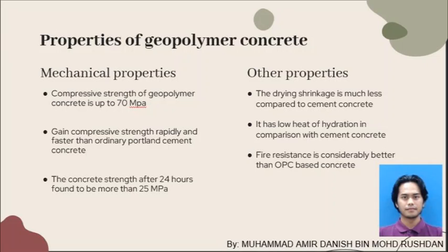The other properties are the drying shrinkage is much less compared to cement concrete. This makes it well suited for thick and heavily restrained concrete structural members. Second one, it has low heat of hydration in comparison with cement concrete. The last one, the fire resistance is considerably better than OPC based concrete.